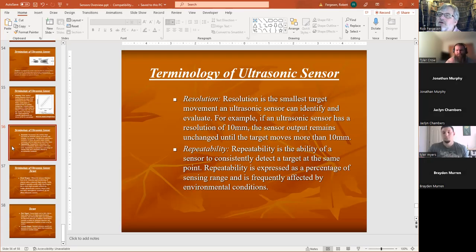You could have a tank filled with gravel where the tank has basically a big funnel. As you drain material out of the bottom of your physical tank, it creates a big funnel-shaped cavity at the top. That's hard to measure accurately. Where do you measure on that funnel? Right in the top, right in the middle, right on the side? It's tricky. So you can have a lot of environmental conditions that make a sensor difficult.